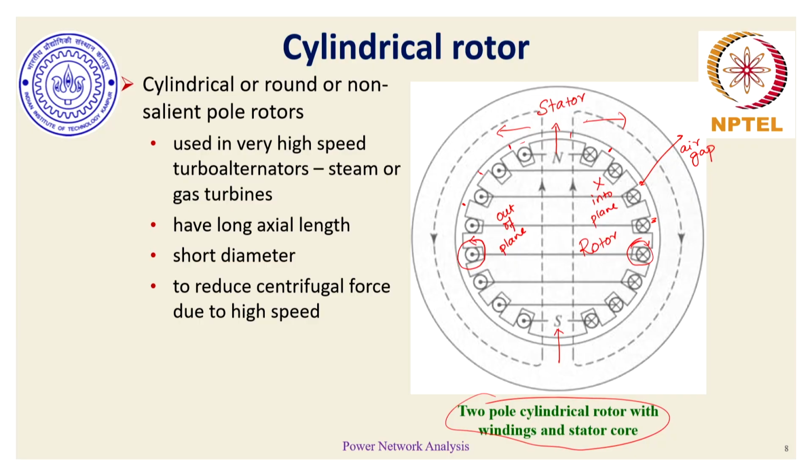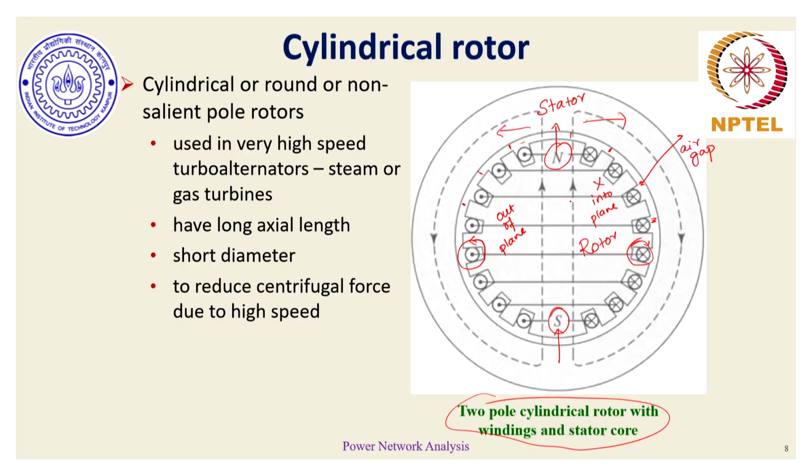So if we apply the same analogy in the cylindrical pole arrangement here, that's what gives us the notion of equivalent north and south poles. That's how this rotor core, which is carrying rotor current, DC current, as shown on the left hand side and right hand side of the particular core, results in this rotor core behaving as an electromagnet having the north pole and south pole marked like this. Now, if this particular rotor is behaving as an electromagnet, and remember in synchronous machines, this rotor is coupled to the turbine for generating mode or some mechanical load in motoring mode. So this rotor is actually not stationary.